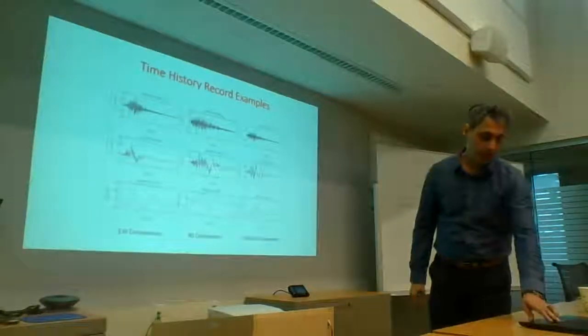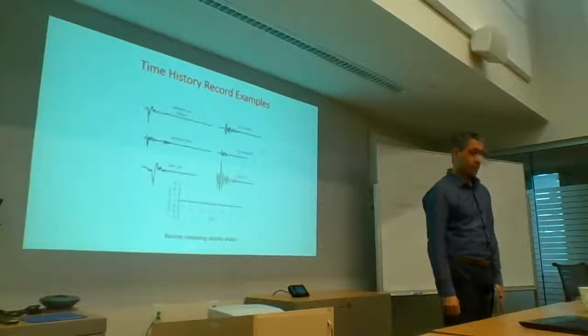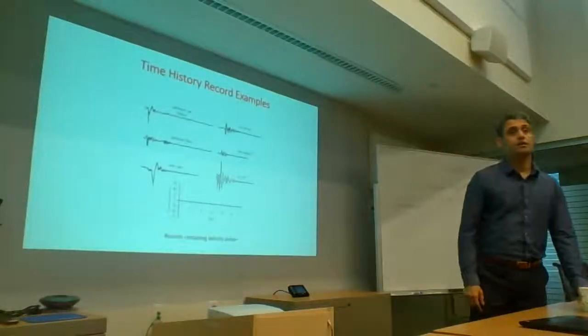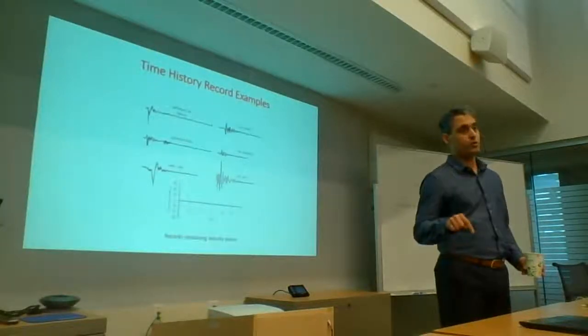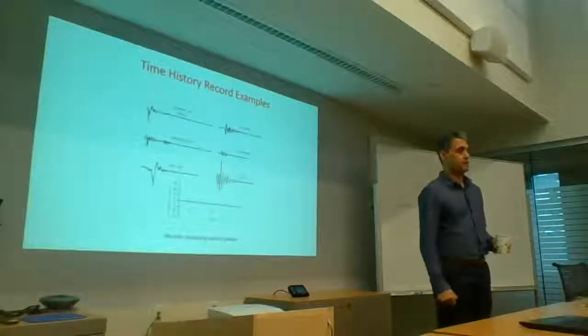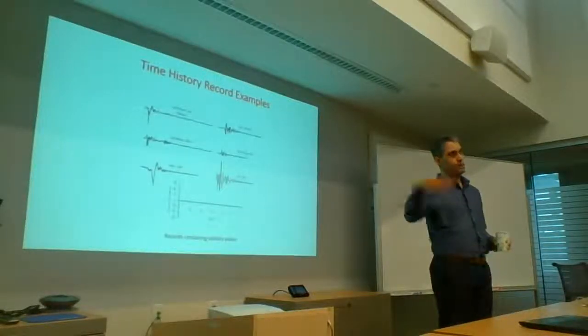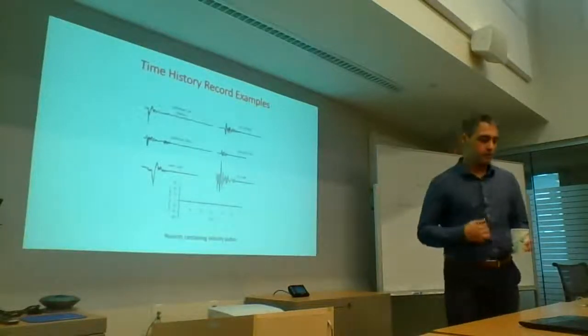If you're close, I've read that your vertical accelerations might actually reach or exceed your horizontal acceleration. So if you're in a near-field situation, that's when the vertical components become quite important. If you're in a far-field situation, they're not all that big of a deal.